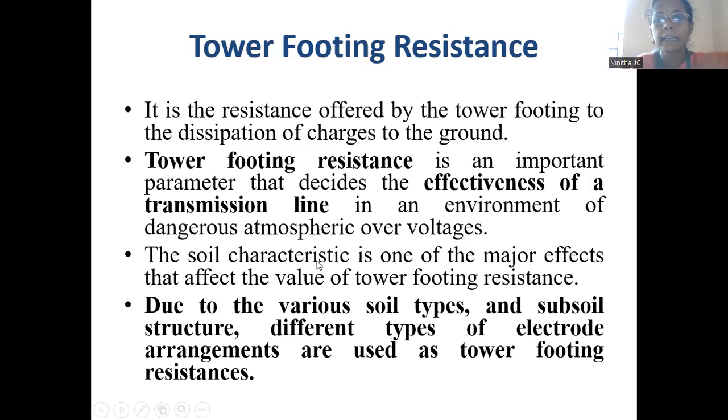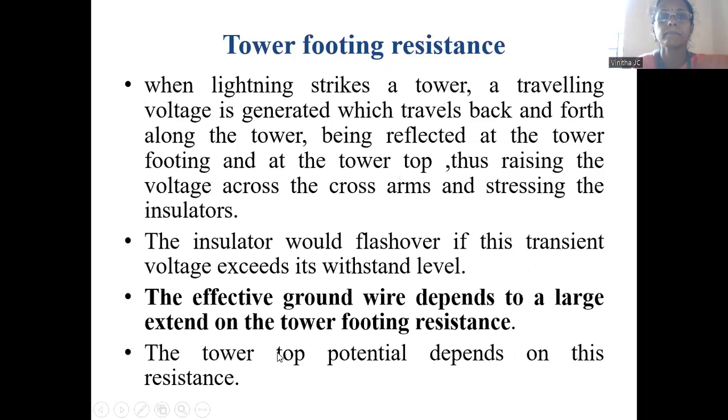The soil characteristics are one of the major factors that affect the value of the tower footing resistance. Therefore, various soil types and subsoil structure, and different types of electrode arrangements, are the main factors that will decide the tower footing resistance.